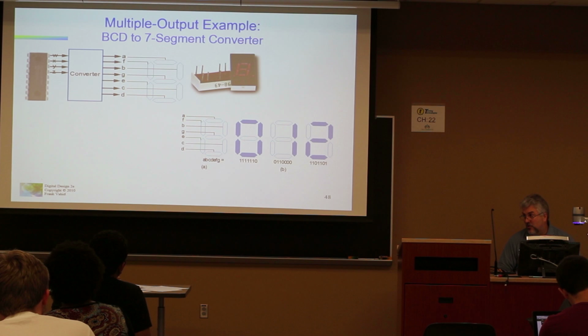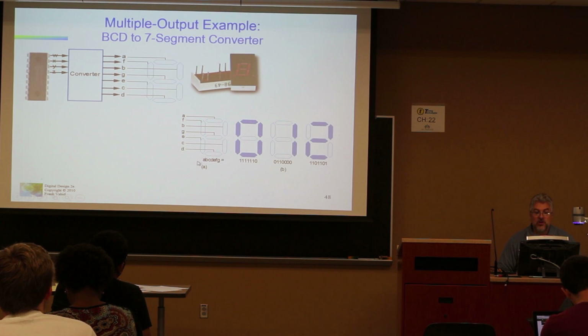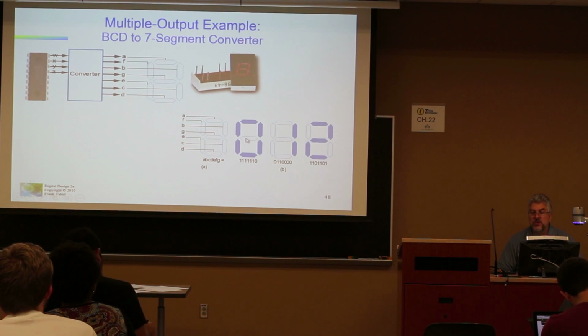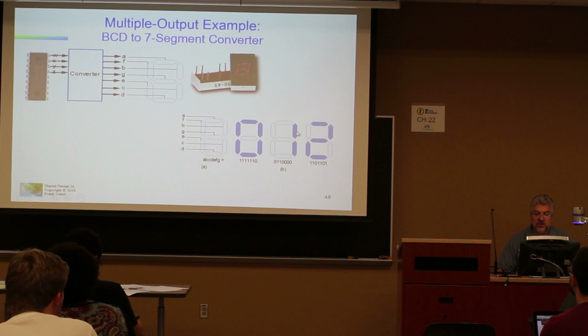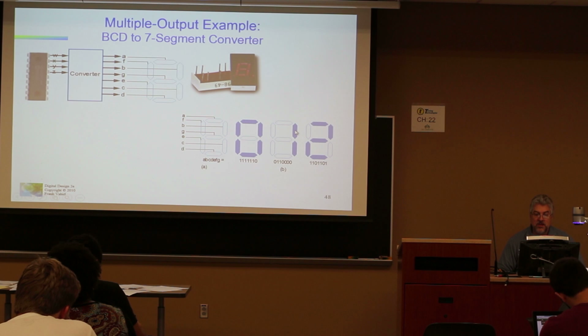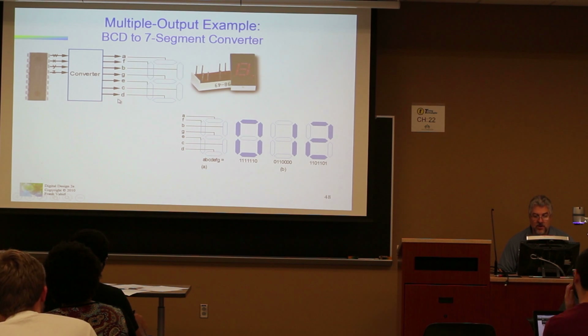And when I say your board, we're getting a whole bunch of boards from Digilent. You will have to show, if I want to show the character 1, for example, this is an easy one. Character 1 consists of elements B and C being 1, starting with A, B, C, D, E, F, G. That turns out to be 7, right?